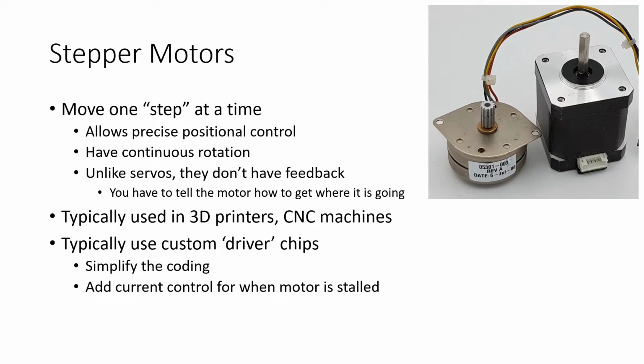And when you turn on your system for the first time, you don't know what position they were left in. So typically, if you're using a stepper motor, you have to run it until it hits a limit switch of some kind. So it's at a known position, and then you can count and keep track of the number of steps that you've told it to move, and hope that you've got a torquey enough stepper motor that when you tell it to move, it actually moves the distance that it's supposed to move.